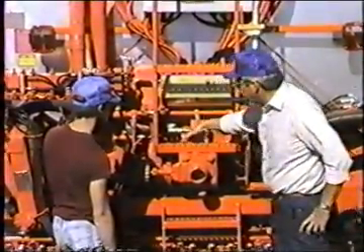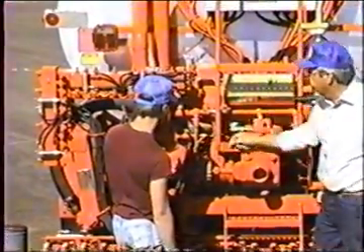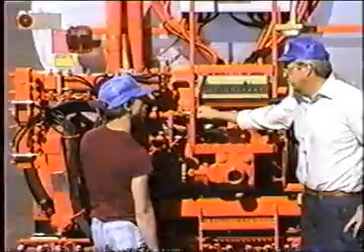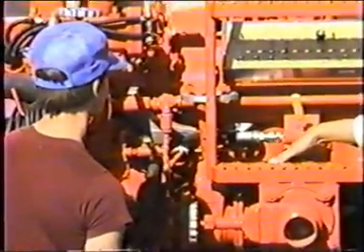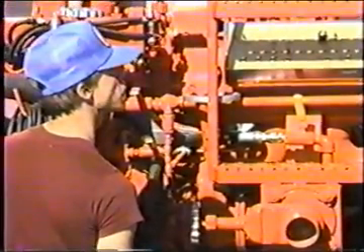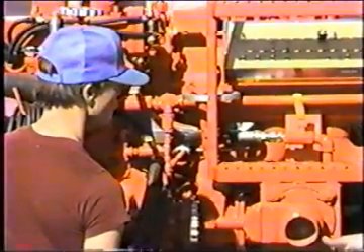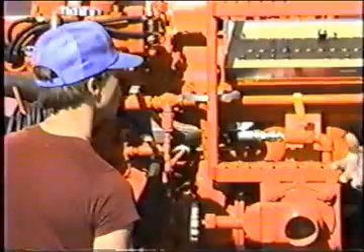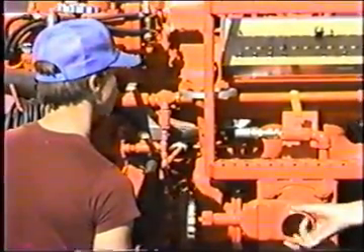Okay, we're coming into this screen housing. Now we're going to go through this valve into the bottom of the pump. This is what we call a pump isolation valve, and it's just that. It's only to isolate the pump from the product in the event that we're going to gravity out of that tank into an underground storage tank, or we're going to pull out of this tank with another pump. Maybe we've gone back to the tank farm or to a hot plant or whatever, and using a different pump than this that we would hook on here.